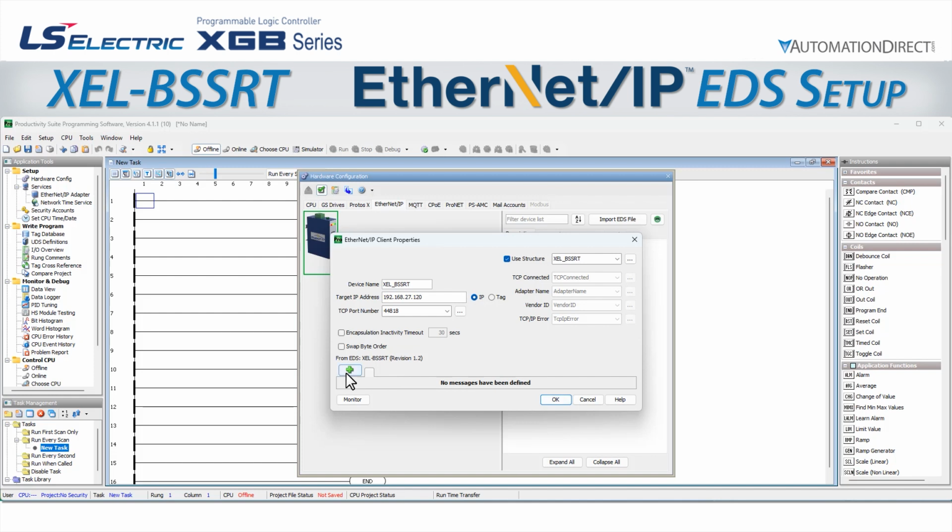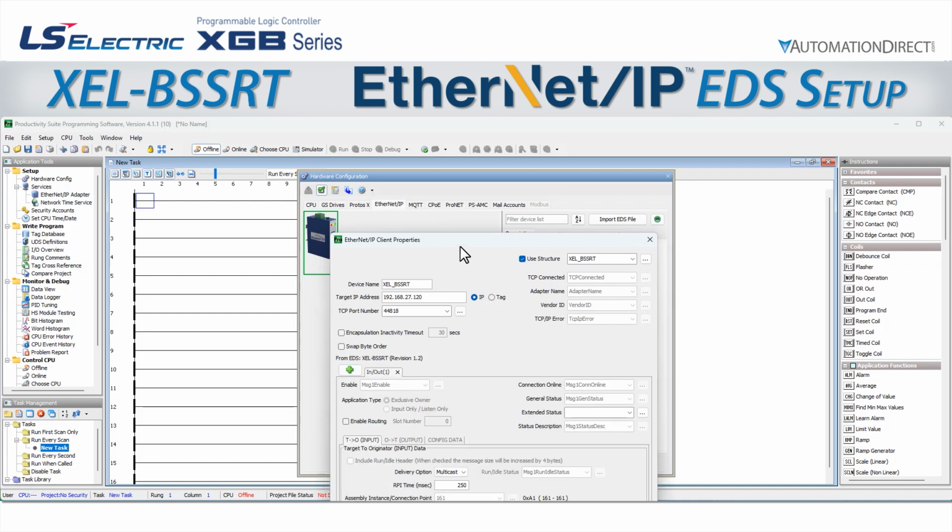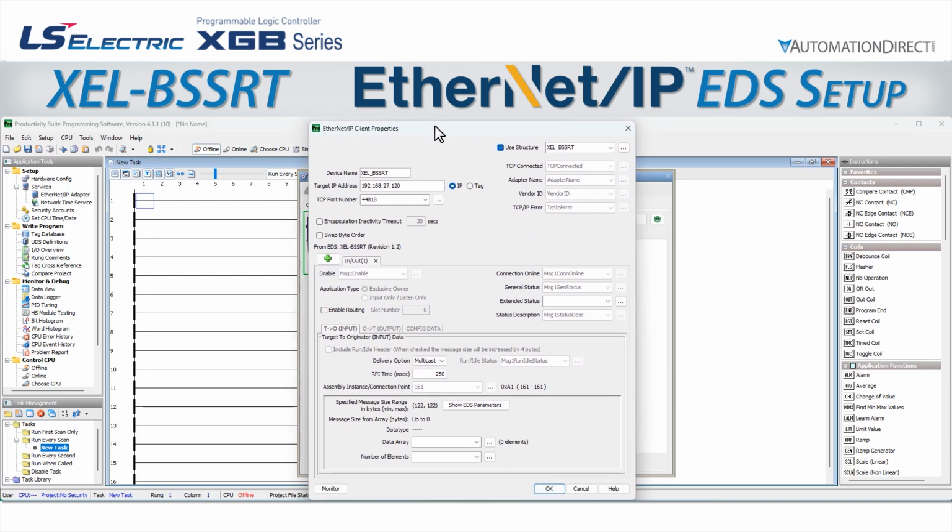Now let's add a message. We click the green plus symbol and we will add an in-out message. Most of the fields will be pre-populated by data from the EDS file, but we want to add a tag in the extended status field. This is technically optional, but most of the troubleshooting for Ethernet IP connections in Productivity will be greatly improved by having this detailed information available. We will call our tag BSSRT_extended status.